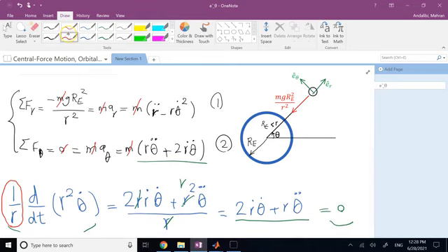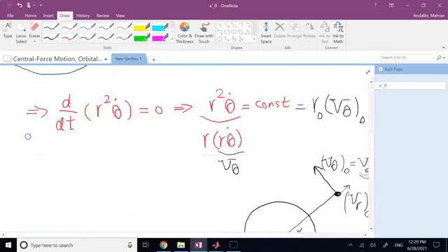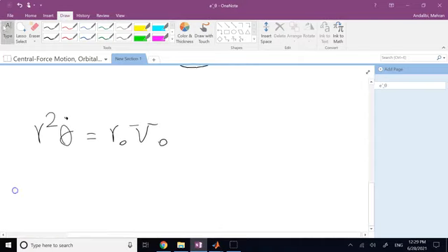If you look at equation number 1, the only term here that is not based on r is this guy here, theta dot, or theta dot squared. If I could somehow replace this theta dot term with an r term, then equation 1 will be fully in terms of r, which means my ODEs are decoupled. So if I can somehow replace the theta dot into 1, then I get 1 fully r ODE, and I can get that. Why? Because now I can use this new equation.